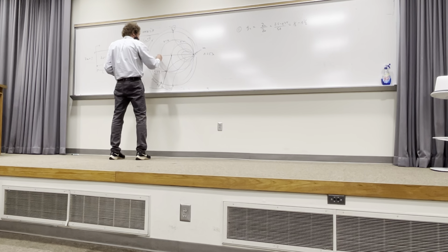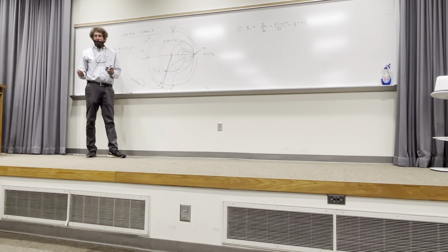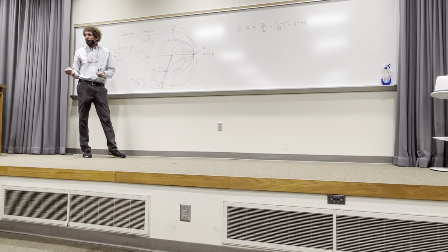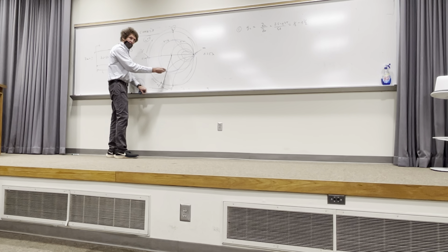Just do that. Now, that circle that I just put here on purple is at a constant radius, which is the magnitude of the reflection coefficient. Do you follow me on this, class? That is a trajectory you're going to move along when you add or subtract wavelengths to this load.